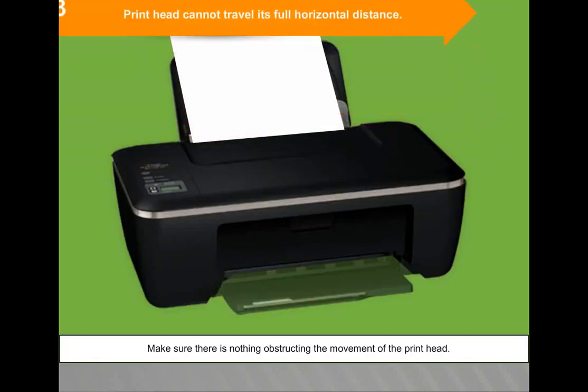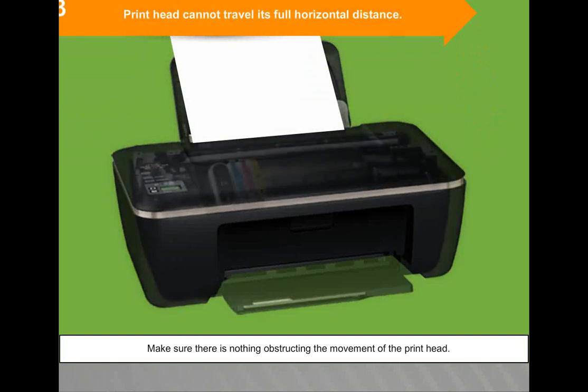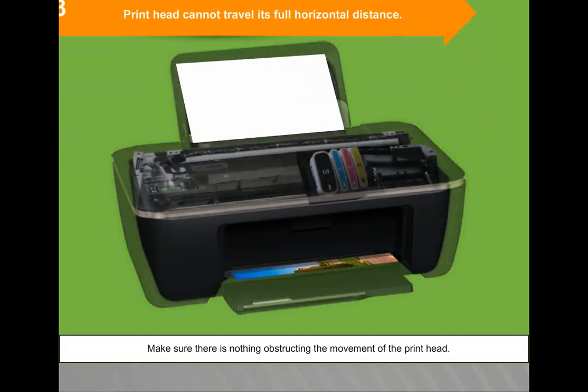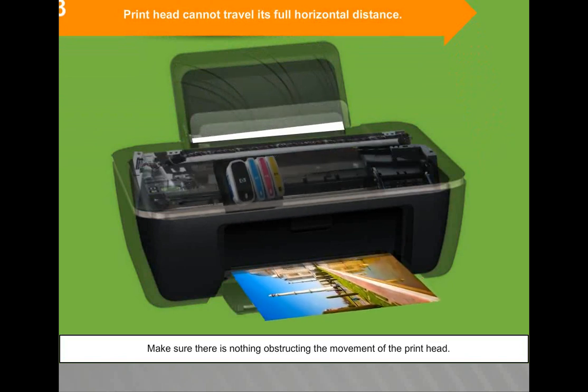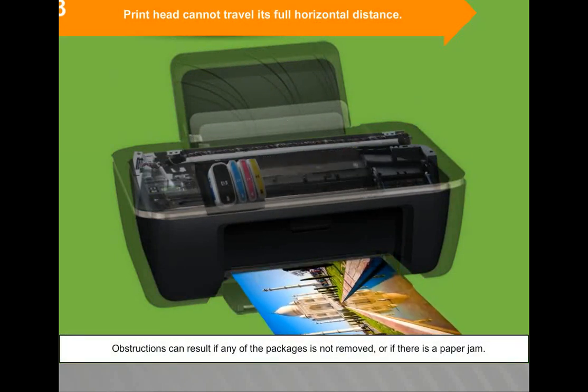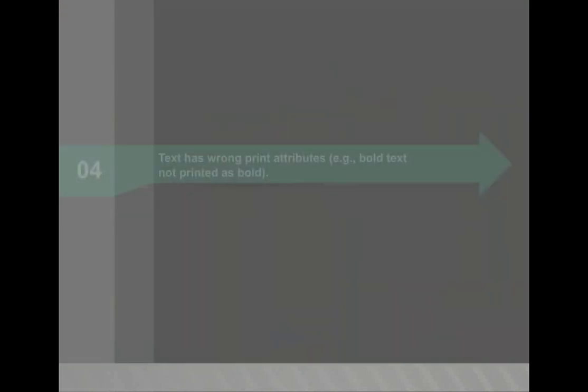Print head cannot travel its full horizontal distance. Make sure there is nothing obstructing the movement of the print head. Obstructions can result if any of the packaging is not removed or if there is a paper jam.